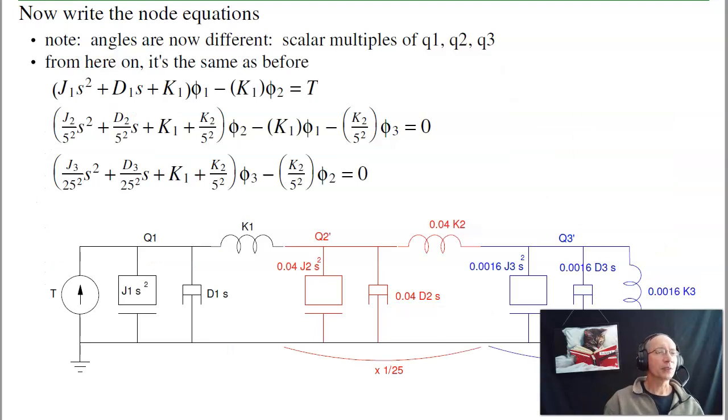Again, what that's kind of useful is gears are used in robotics. If this is the motor over here and the robot arm, if I have a 300-to-1 gear reduction, then the load relative to the arm, as seen by the motor, is scaled by the turn ratio squared. So the arm, whatever you're picking up, is scaled by 1/300 squared. So the gear basically makes the outside world irrelevant relative to the motor. All the motor really cares about is if I can control myself, control the motor's angle, I can control the tip position of a robot through the gear. So really robot control is just can I control a DC servo motor.